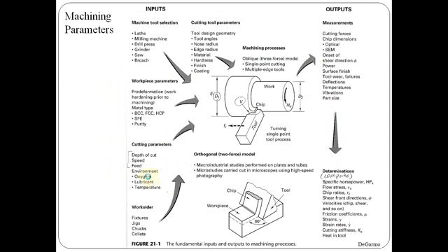So in general, the inputs are the machine tool, a cutting tool, and the workpiece, which has to be operated in a proper setting with the support of work holding to ensure the cutting process. The machine tool is decided based on the size and shape of our work part. The cutting tool depends on the operation to be performed on the work part, and its nomenclature, material, hardness, finish and coating matter, as it has to withstand high forces sometimes.